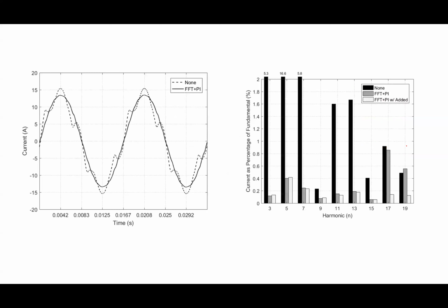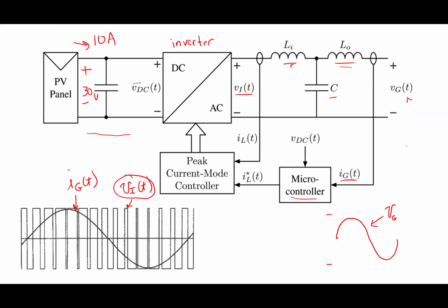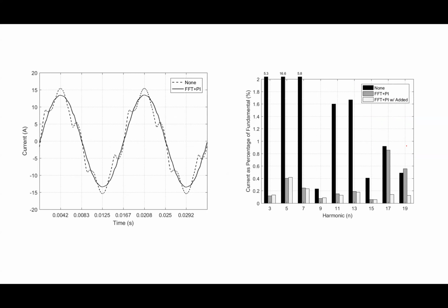Right? So one of the things that we often do, and we use this a lot in power, is this: in that inverter that I was showing, when I first run it, that waveform probably doesn't look as clean as it is. All right. So here's the situation. Here's a voltage. This is actually a current, that dashed waveform there. What I'm showing here is at each harmonic, what percentage of that waveform I have at that particular harmonic. Anybody know what that is?